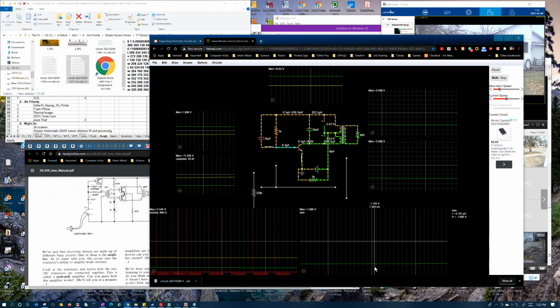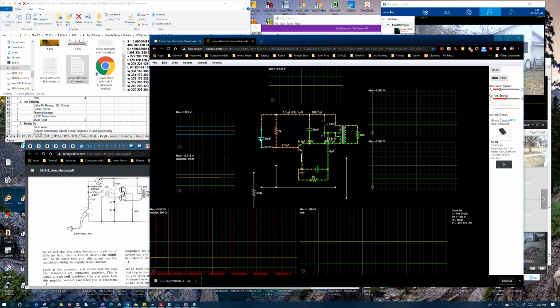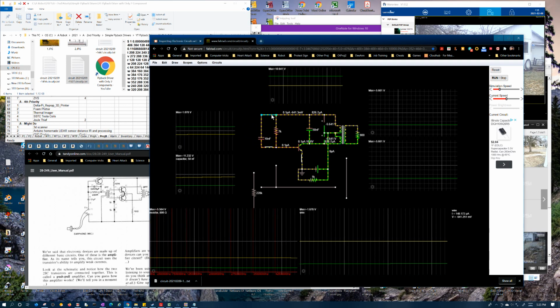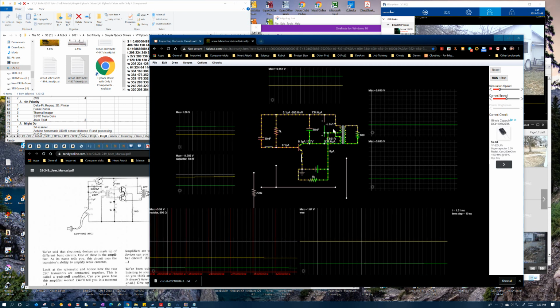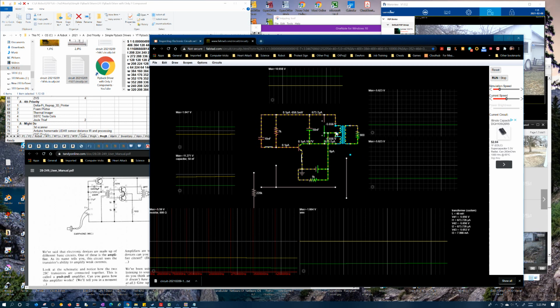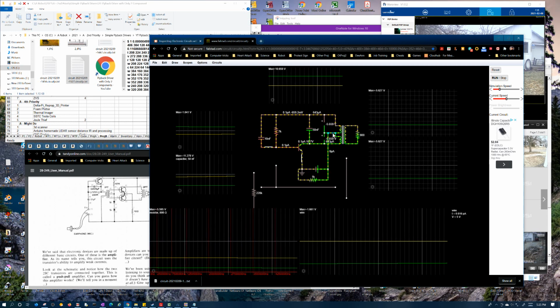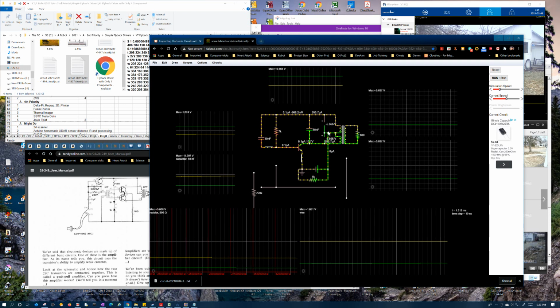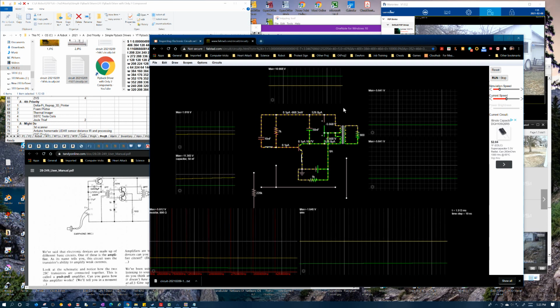That voltage is well below ground now, and it's because this capacitor voltage is above ground but being forced low, because this is low because it's got these reverse voltages across it. Again, this is like 5 volts opposing our positive 5 volts, like we've got a battery's negative terminal tied here and its positive terminal here, counteracting the voltage on this battery. So it's that and then some.